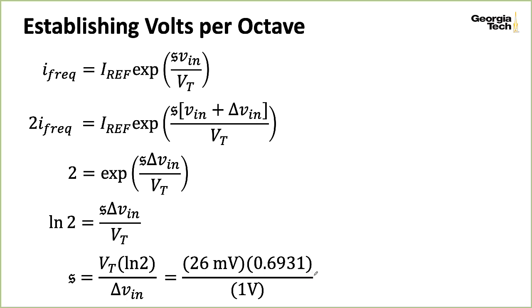And now we get to pick what volts per octave we want. Buchla systems use a 1.2 volt standard, and that's kind of nice because it corresponds to 100 millivolts per half step, which is the pitch distance between keys on the piano. But most other manufacturers use the Moog standard of 1 volt per octave, which is easier to remember, and is kind of nice if you're using a digital voltage generator as a piece of test equipment that lets you change the first digit to the left of the decimal point by an increment or decrement of 1 each direction, because that corresponds to an octave.